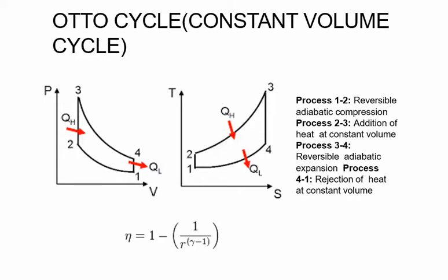During a complete cycle, the gas returns to its original state of temperature, pressure and volume. Hence, the net internal energy change of the system is zero. As a result, the energy added to the system must be offset by energy that leaves the system. In the analysis of thermodynamic systems, the convention is to account energy that enters the system as positive and energy that leaves the system as negative.